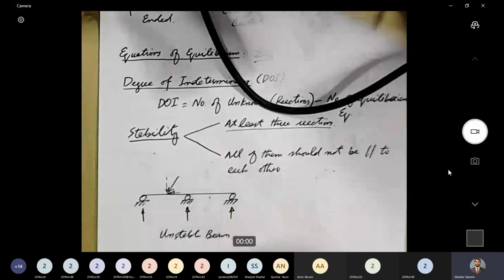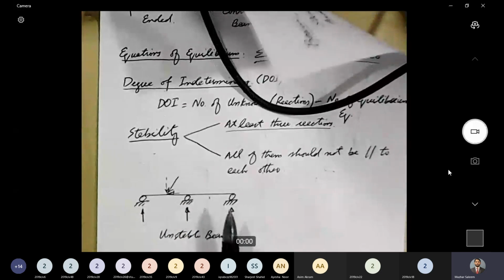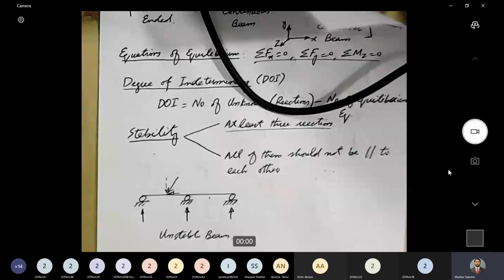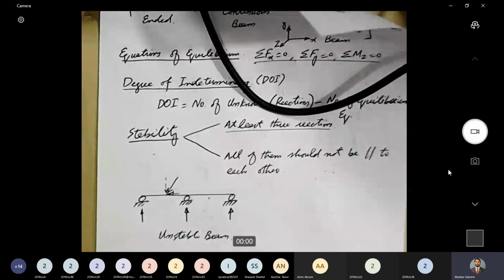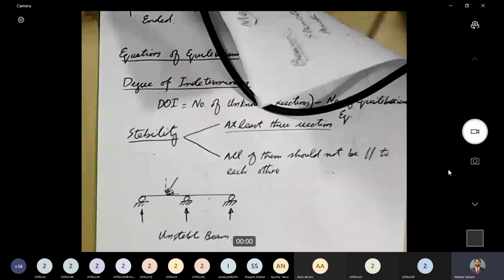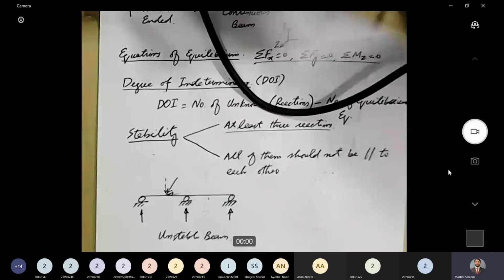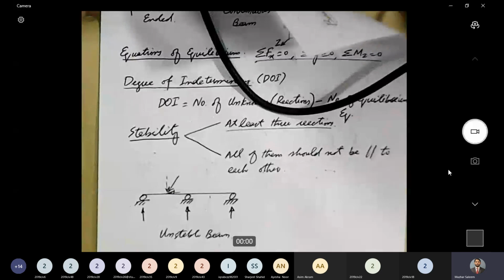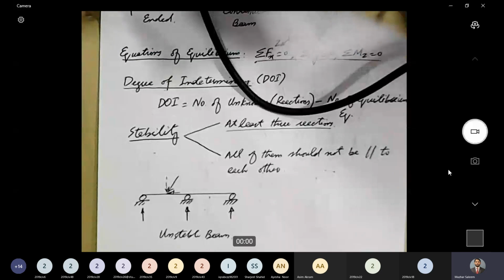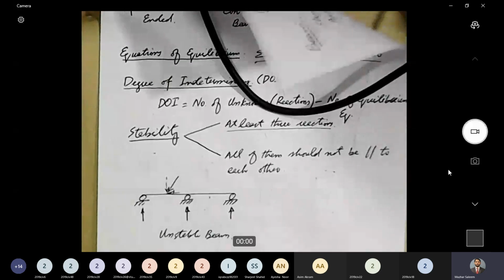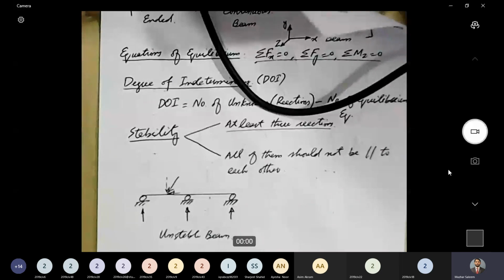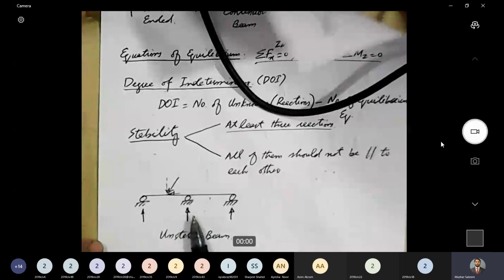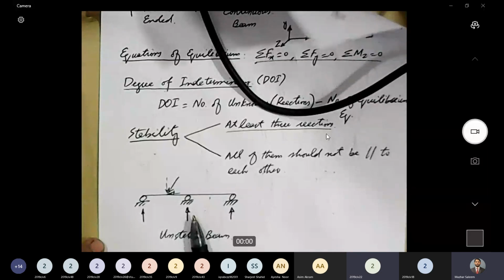And as he pointed out, and as I said earlier as well, even roller support has the ability to provide a small magnitude of horizontal reaction. But at this point, we will be ignoring that. We will not say that there is slight horizontal force, so the self weight will make it stable. No, if it's a roller support, we will assume the horizontal reaction is zero. Again, just for clarity, practically it will be able to provide some resistance, but we do not want to depend upon that small magnitude of resistance. Okay, is that clear? Yes, sir. All right.